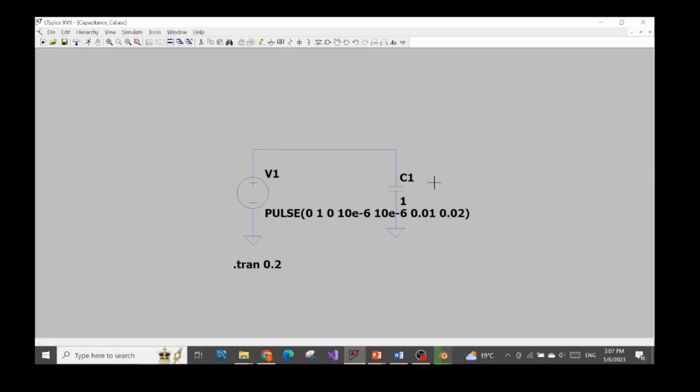And one more time, as a reminder, here we need to apply 1 farad to the capacitor in order to simulate the result of the voltage and also the current going through the capacitor. But when we already have the measured voltage on the capacitor and the current, we will assume that we don't know the capacitance here is 1 farad. Then based on the measured voltage and current, together with the calculation method in the frequency domain, we will derive that the capacitance of capacitor C1 is approximately 1 farad. So now let's run the simulation in the time domain.